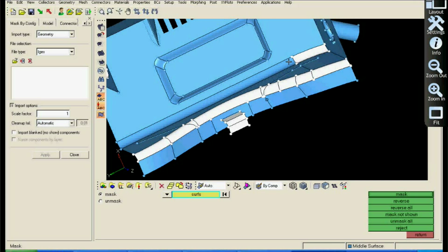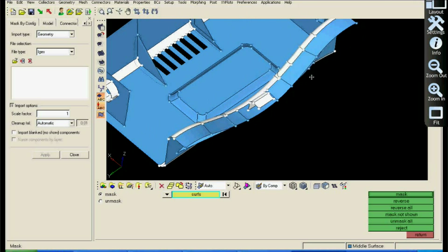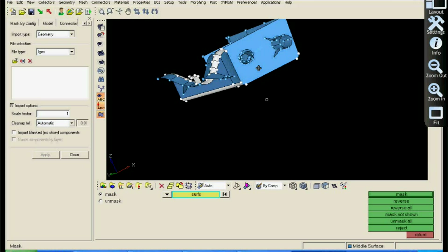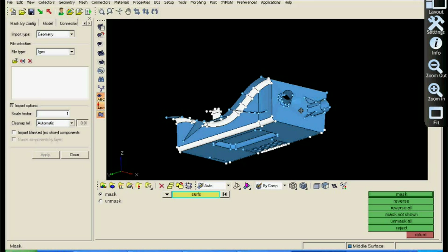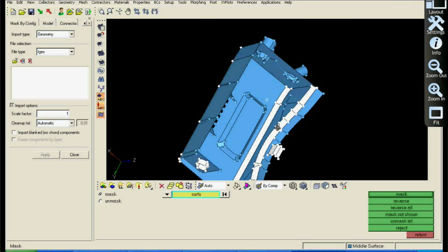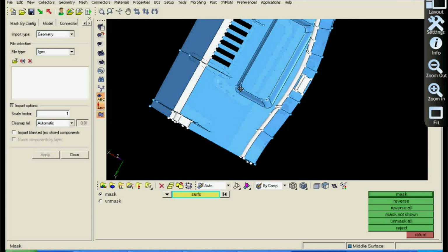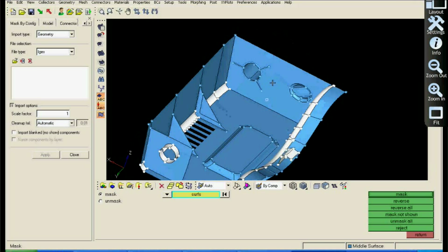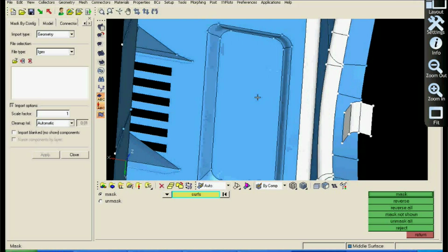These are the areas I have just highlighted, not defined actually, to show you where I want my map mesh. So it's the same number of elements, and it will have a nice flow of elements throughout. One can also think of doing the same for all these surfaces here, but one can also eliminate them. It depends. Alright, so I will just go ahead with the mesh